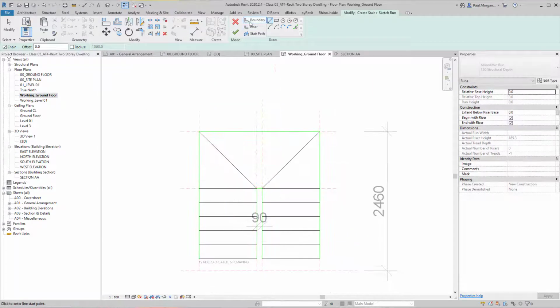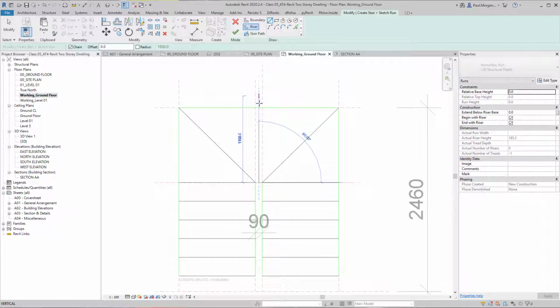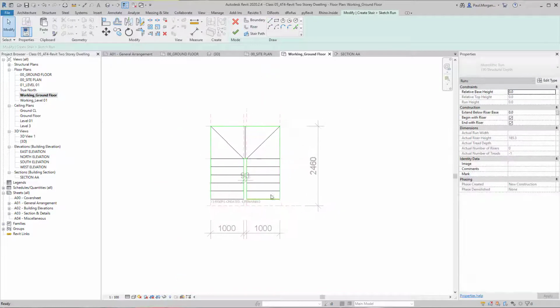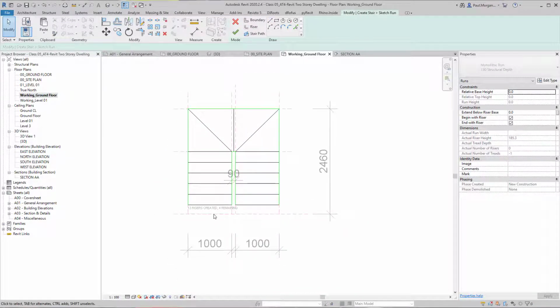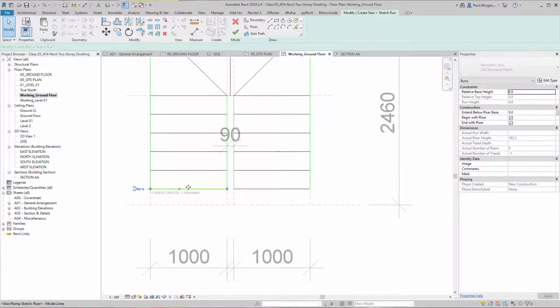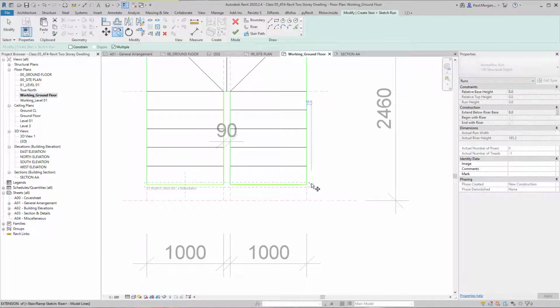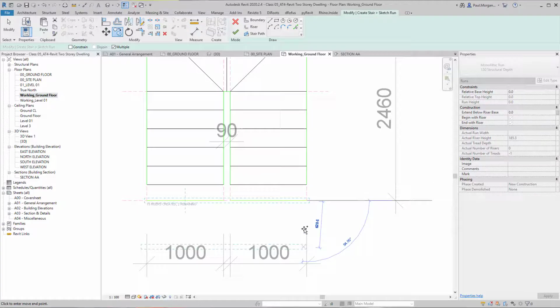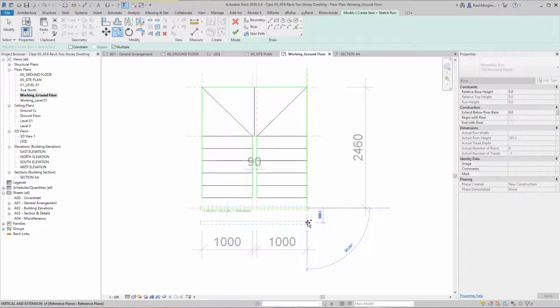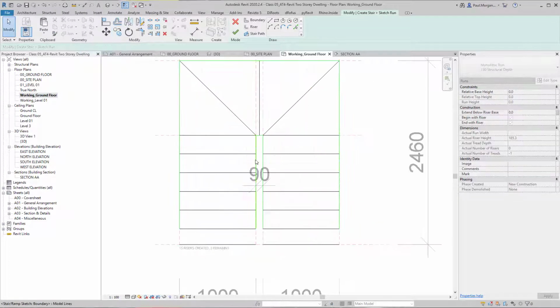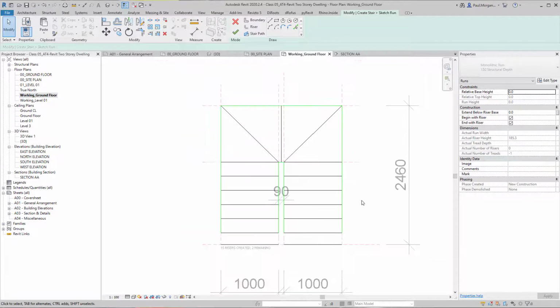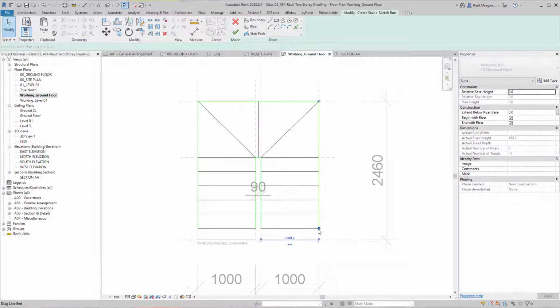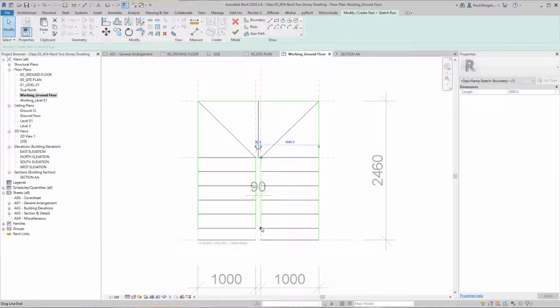And then I need to take one more riser line and go from the central point of the stair and go like that. Now the last step I need to do is I still need some more risers, so I'm just going to double click. Let's go another one, 2 remaining. Okay, so I have 2 more risers remaining. So what I need to do is that's our maximum distance for our staircase. I just need to extend these lines down to here.